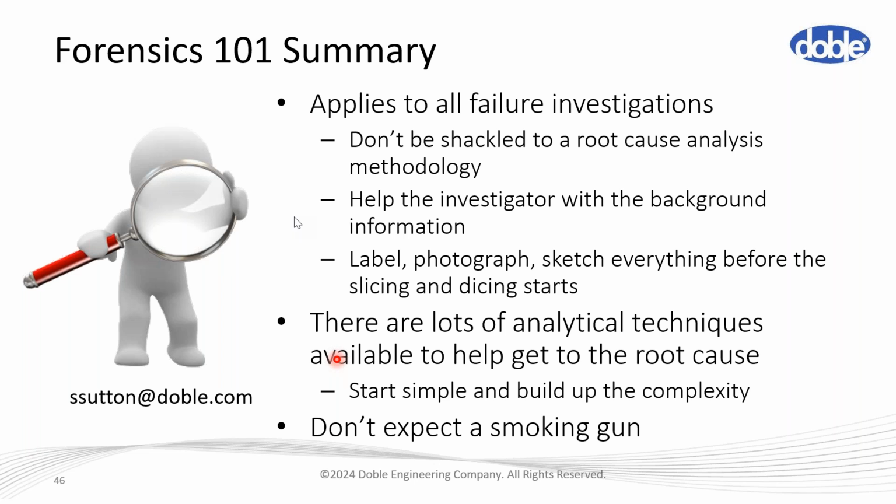Do we see evidence of partial discharge regularly in XLPE joints? The answer is no. A well-made joint should not have any discharge in it. As I said earlier, the cables are factory tested, the joints are factory tested. It's only when they get to site and people have to put them together on site that problems arise.